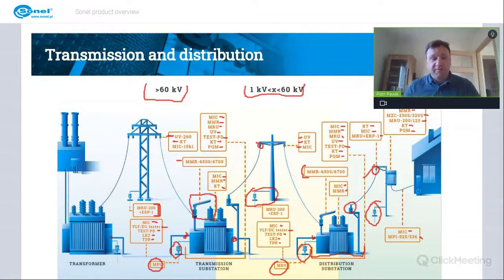So that happened just recently. I was showing to people from an energy company, who wanted to locate which house in the residential neighborhood is connected to which breaker in a breaker box. So we were connecting the current clamps of the locator's transmitter near the breaker, and then we were following with the tracer to a particular house. Okay, so that was the transmission and distribution.